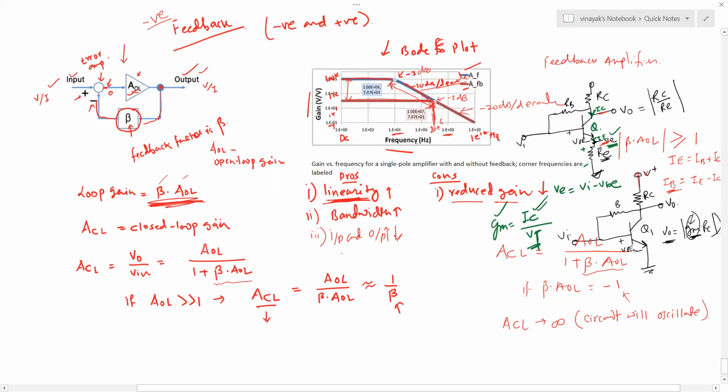Yes. Let me explain again. So if there is a change in IC, there is a change in voltage drop across VE, because the IE will change here. So VE changes, it means the voltage at the base will also change to maintain the constant VBE and again regulate the current IC into the circuit. So kind of negative feedback we see there.